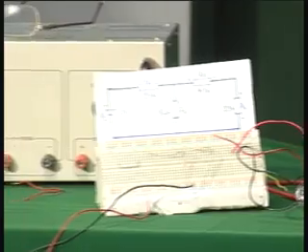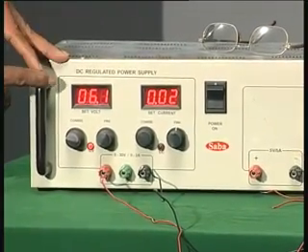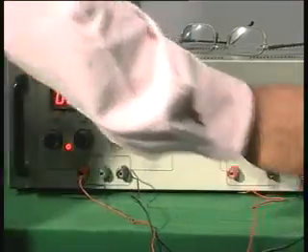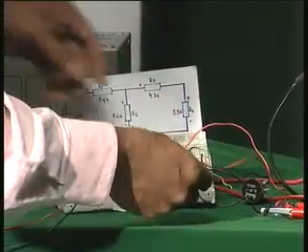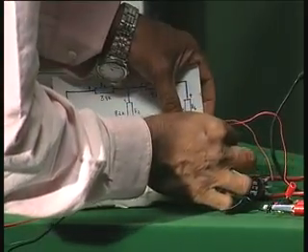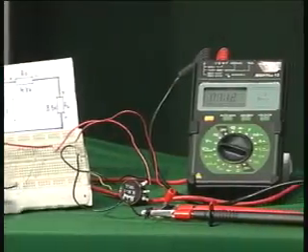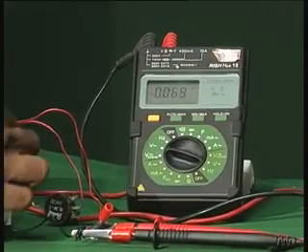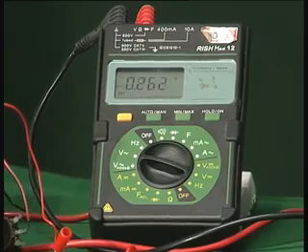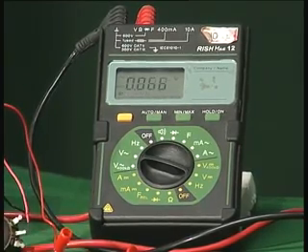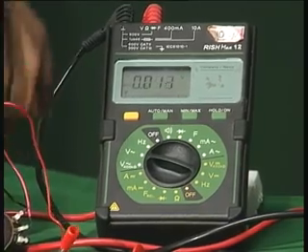We have set the voltage source to give an output voltage which is equivalent to Thevenin's voltage. Now I will connect this across that smaller, simplified circuit, and now I will measure the output voltage using the voltmeter. So I connected the voltmeter across the load 3.3K.